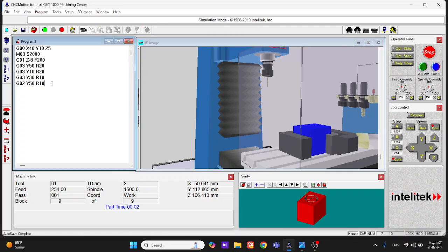First of all, we will go back to the 0 position, but a little high from the specimen so as not to damage it. So I will return with G00, and for Z I will put 10 plus. It was -8 on the specimen, so I should put something positive, even more than this, to come up above the surface with a safety distance between the surface of the specimen and the tool. Then when I come up from the depth, I need to change the tool.